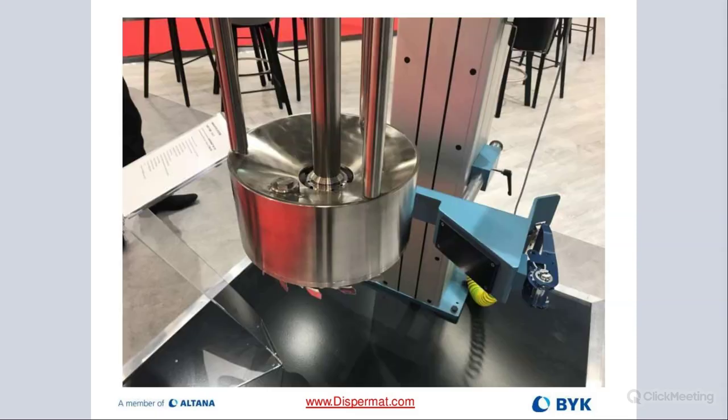And the reason why we don't want to have a screen on the side is for cooling. So basically, our basket mills are double walled. So these bars that you can see here that are holding the basket, they're actually cooling channels. So we're sending down coolant or cold water in and out of the basket. So come in on the right, leave on the left. And then basically the entire basket, even the top portion, is properly cooled. This is where we put in all of our energy. So that's where we want cooling. If we had a screen on the side, we wouldn't be able to cool that portion.